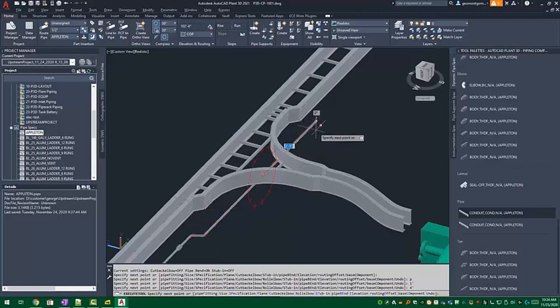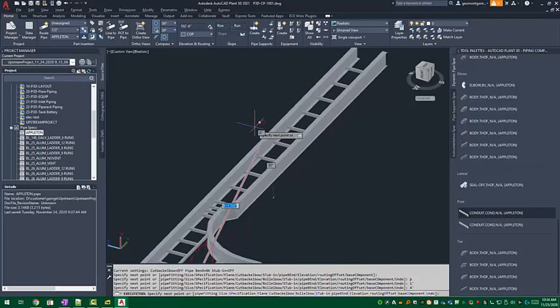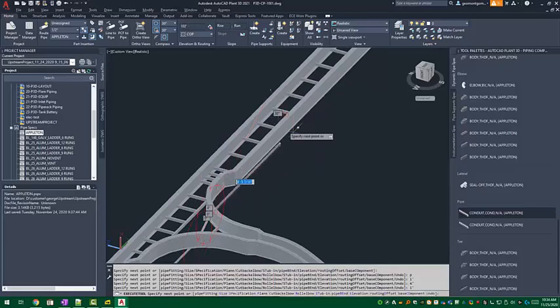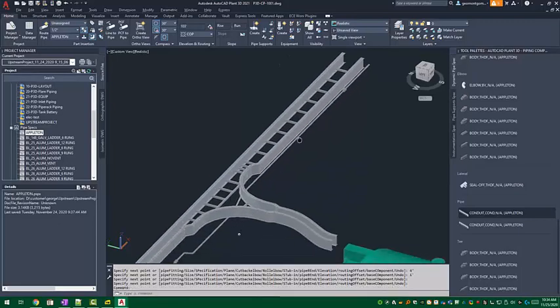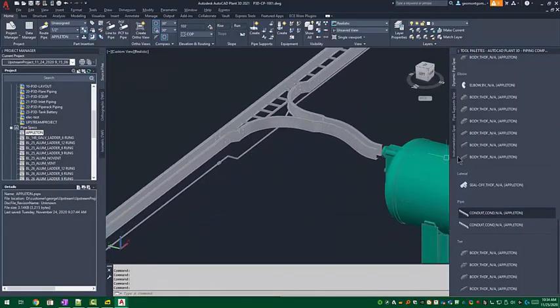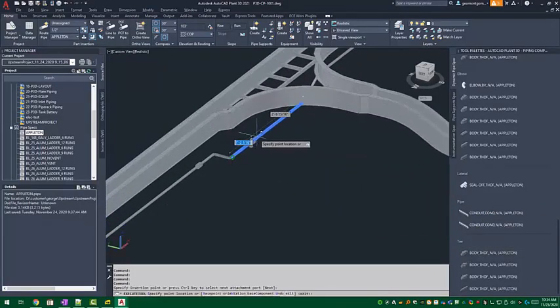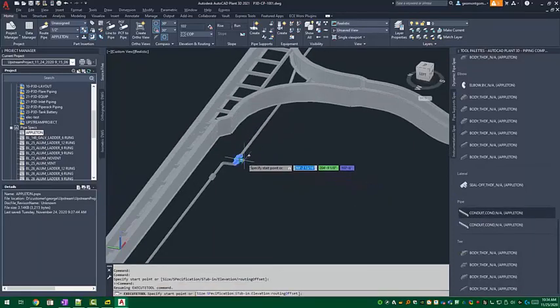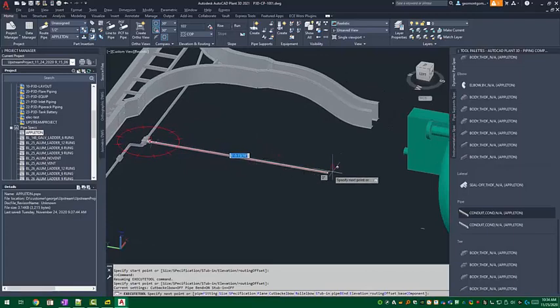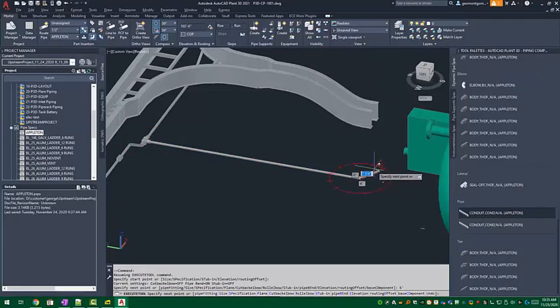I'm using the P key to change my plane while routing the conduit. After that major route has been placed, I'm going to select a conduit body that I can use to tee off this route and complete a route to one of my existing skids. Again, I'm using P to alter my existing route to be vertical.